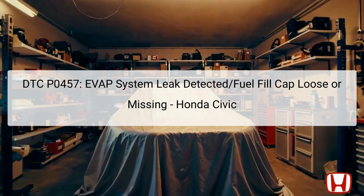The DTC P0457 is a diagnostic trouble code that indicates the EVAP, evaporative emission control system, has detected a leak or that the fuel fill cap is loose or missing. The EVAP system plays a crucial role in preventing fuel vapors from escaping into the atmosphere, thus contributing to air quality control. The fuel fill cap, located on the fuel tank filler neck, must be properly secured to maintain the integrity of this system. When the system fails to retain pressure, the vehicle's onboard diagnostic system will trigger this code.